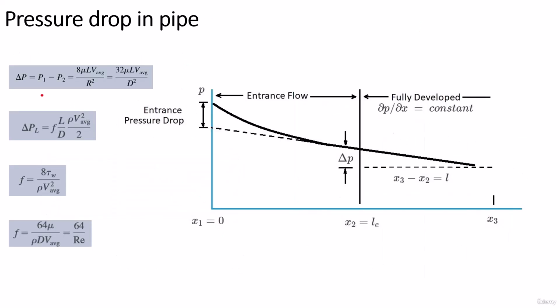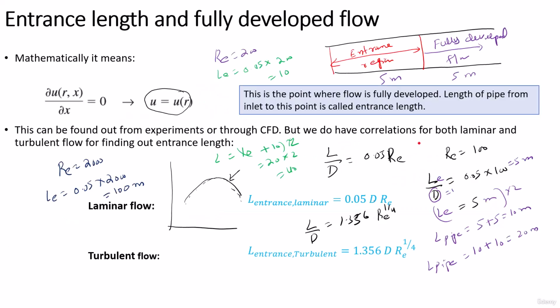And this is the pressure drop formula, which you know very well. It is not a good idea to compare the analytical solution with the CFD in the entrance region, because these formulas are made for when the flow is fully developed, except for the one formula that finds the entrance length itself. Every other formula is only valid when the flow is fully developed.